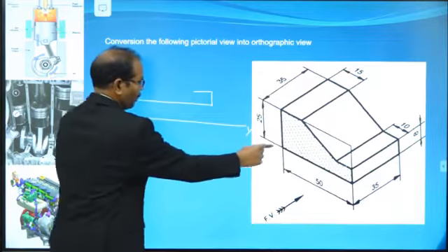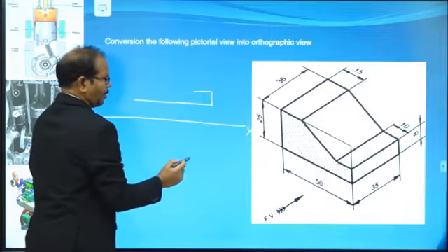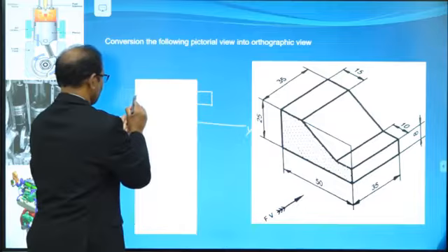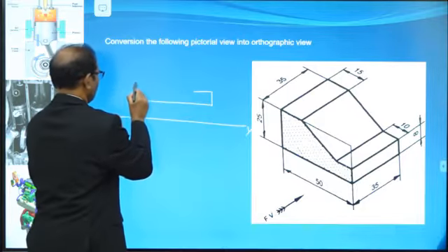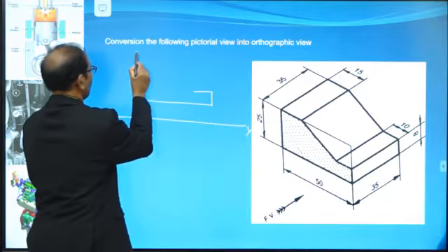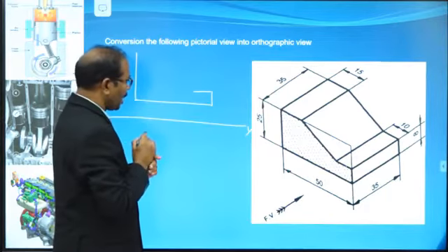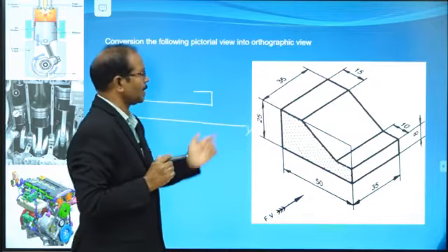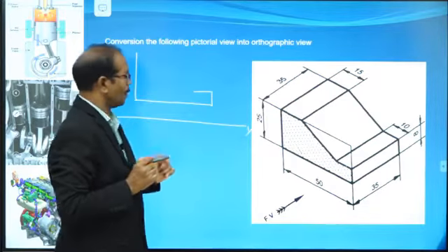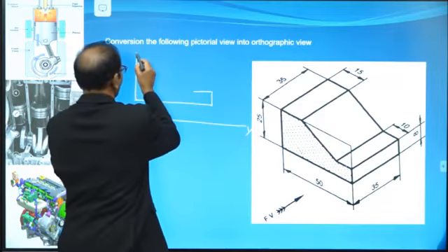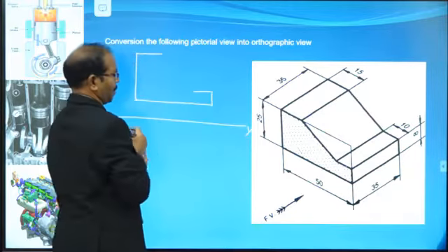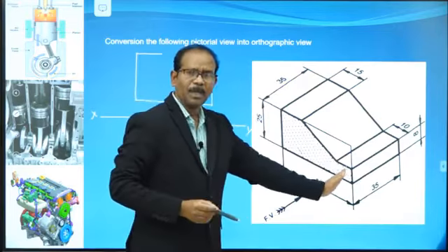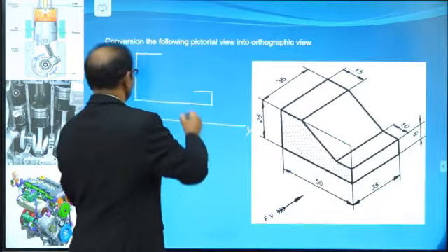Stop there. Again there is one more vertical line on the left side. You can draw this line at a 25 mm height. From there to there, one more horizontal line is there. Say the length is 15 mm. Now draw the horizontal line, 15 mm. Now this point is already there. Just simply join that slope line.